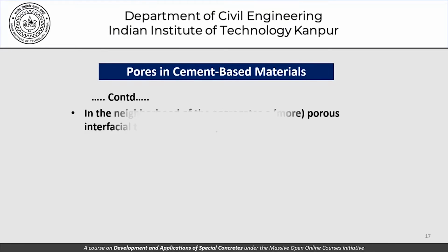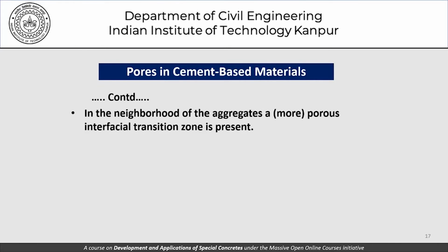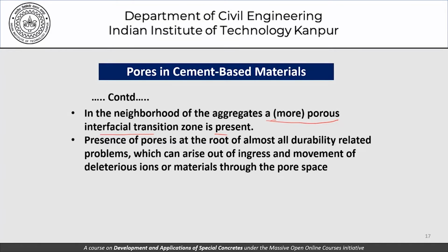Continuing further, in the neighborhood of the aggregates, a more porous ITZ is present, and that's what we talked about just now. Presence of pores is at the root of almost all durability related problems which can arise out of the ingress and movement of deleterious ions in materials through the pore space. So that's why we really need to have a very good understanding of pores and porosity in concrete.